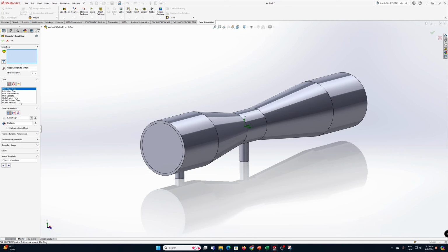For this scenario, you would use the first one, flow opening. Go to inlet velocity. You also have different parameters. The first one is normal to the face. That means we will use a direction perpendicular to the face that you select. The second one is your height, like a sweep in the system. So I'm moving like this. And finally, you can put the value in vectors, in the different components X, Y, and Z. I would use the first one, normal to the face.